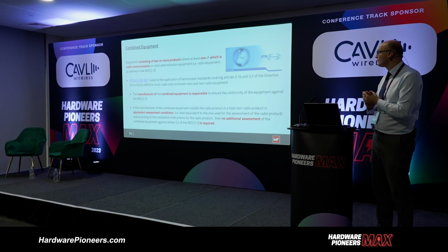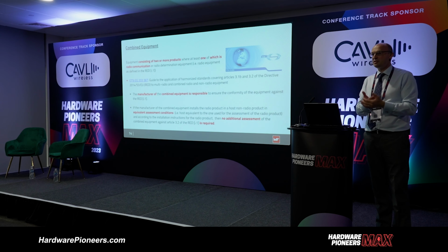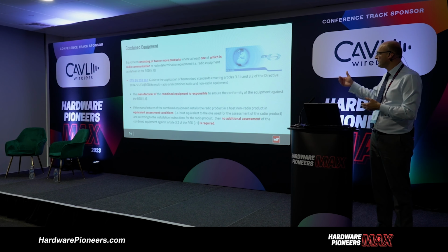I've not come across any customers yet that can actually fulfill this requirement. And as I say, when most radio equipment module manufacturers are qualifying and certifying their modules, the module itself is too small, so it has to go on a daughter board or on a motherboard. That motherboard normally has additional power supplies. So what it's saying here is for you to carry that all across without any additional reassessment, you need that eval board. Well, that eval board could be twice the size of the product that you're designing the module into. So most of the time, customers are unable to meet that requirement.